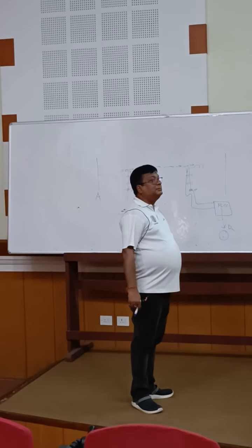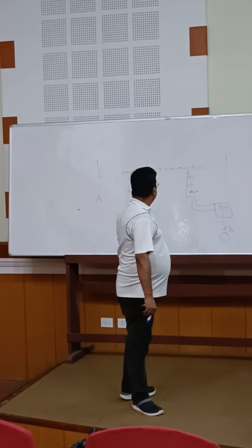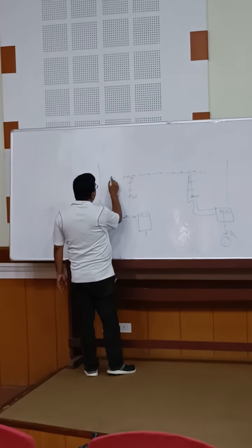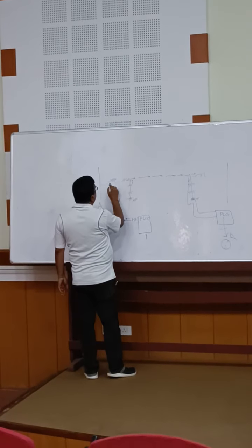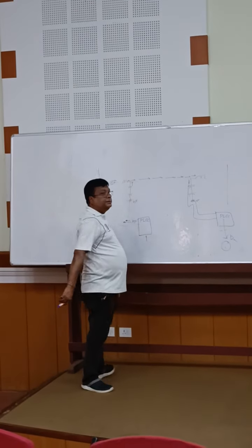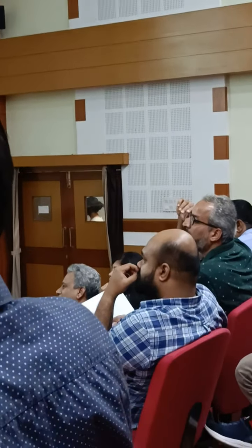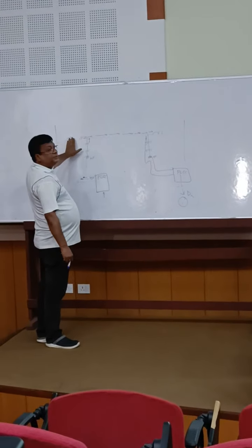Both the frequencies are traveling. Yes, power is also traveling at 50 Hz. The power and the communication both come on the same conductor. So first it will enter into the substation. Now for the high frequency signal, the wave trap is a problem. For the low frequency signal, 50 Hz is a low frequency, no problem.